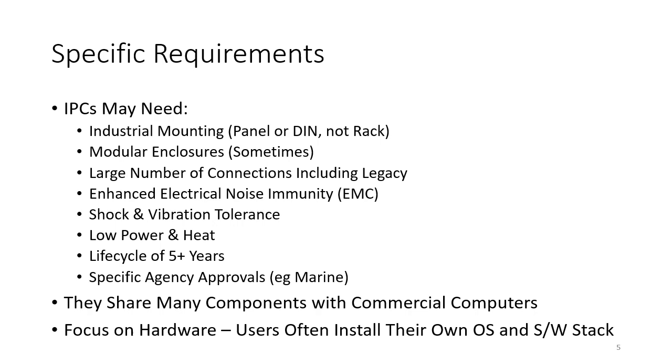So IPCs are often constructed from metal enclosures and they have a higher level of EMC capability. Shock and vibration, we talked about that, but IPCs often need high levels of shock and vibration technology. Vibration is continual movement, so maybe there's a large motor nearby and that can lead to vibration. Shock, again, think about that railroad application.